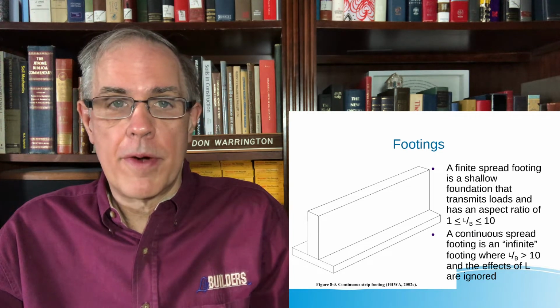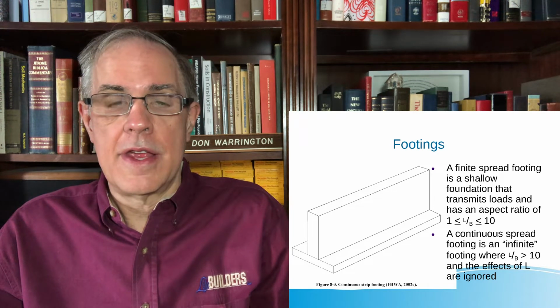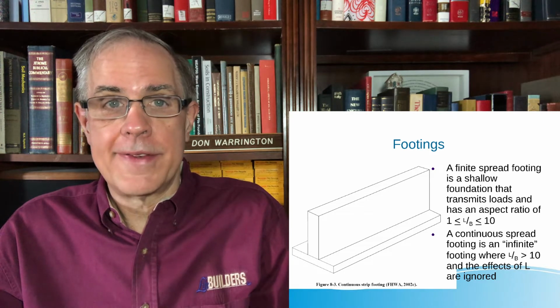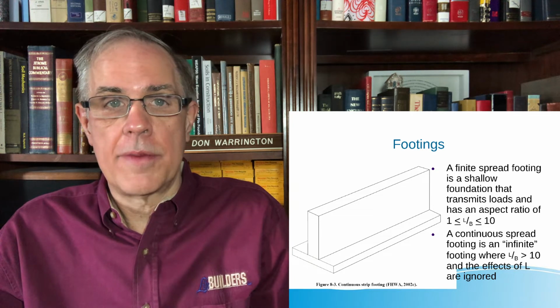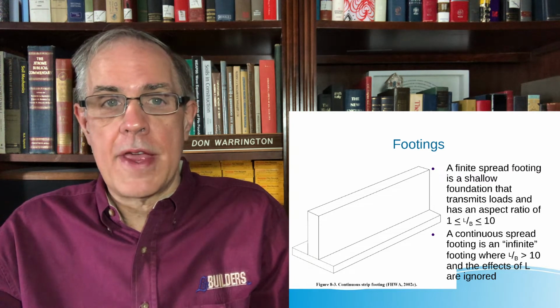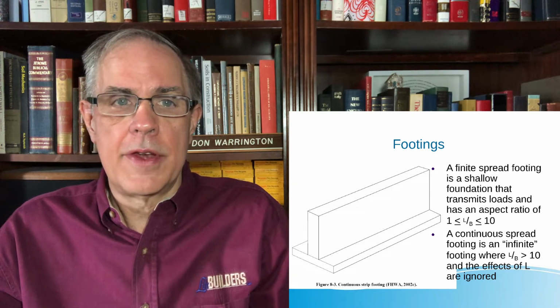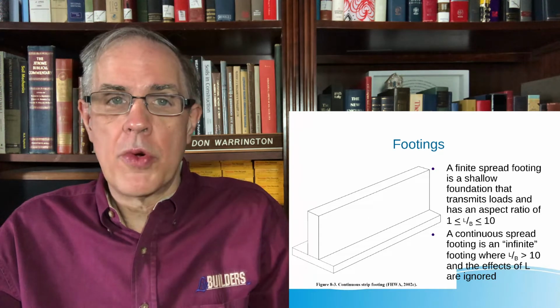But for purposes of design, if a footing's length is 10 times or more its width, in other words, L over B is greater than 10, then we consider it and design it as a continuous footing. If a foundation is less than that, then it's usually a rectangle, down to the point where the dimensions are the same, and it's a square foundation. That's an important definition.